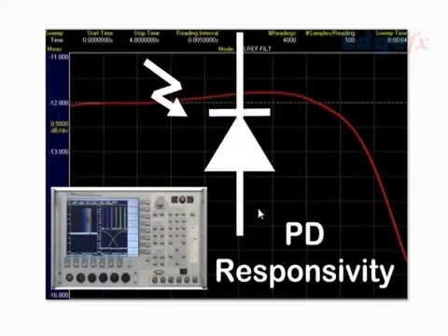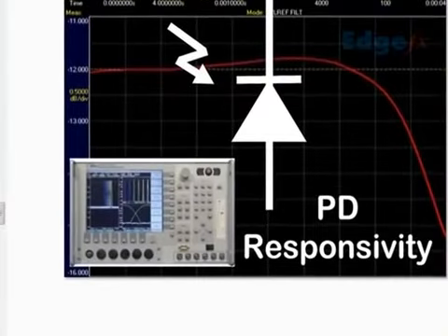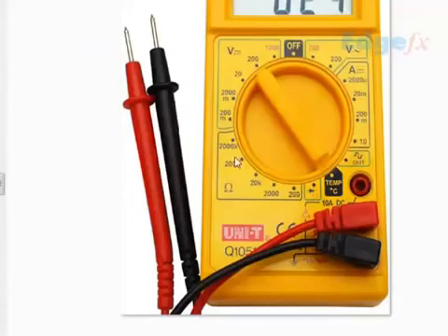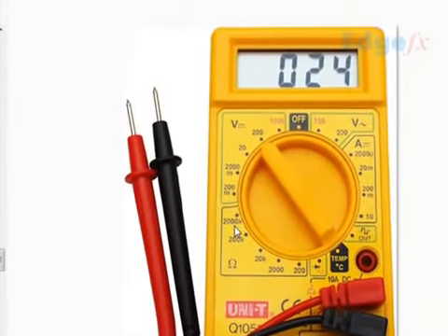And the trick is you have to measure it in the resistance mode. We know that we have in the multimeter a resistance mode. Go to the resistance mode, select 2000K. This is 200K, and select 2000K, and then start measuring it.